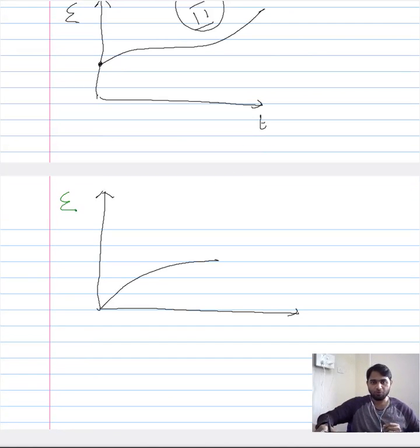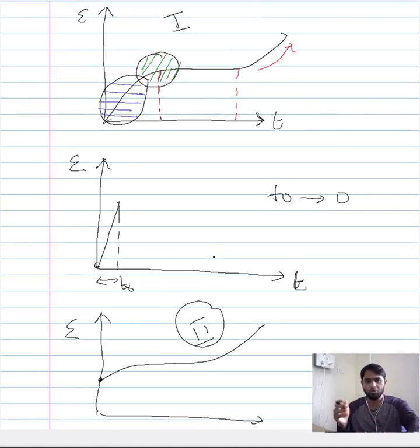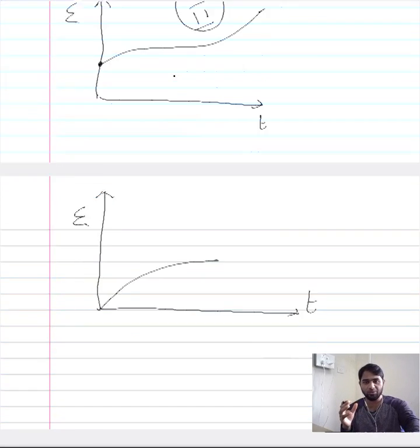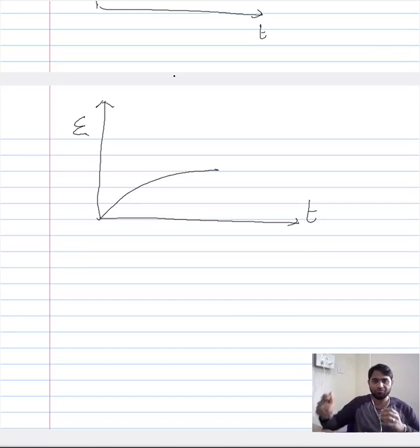Now immediately following the instantaneous elongation, the rate at which the material is elongating decreases, and you could see there is a visible decrease in the rate at which the material is elongating, and this would form the second phase. So you have your instantaneous elongation, and there is a gradual change in the rate of elongation, and this gradual change ultimately leads to a visible state in the creep curve.